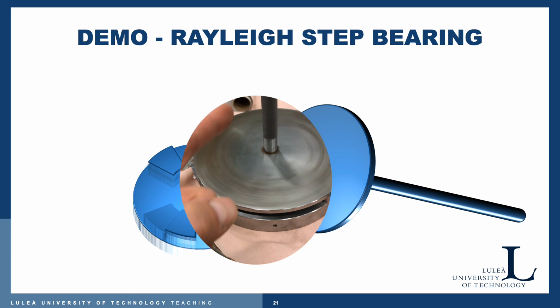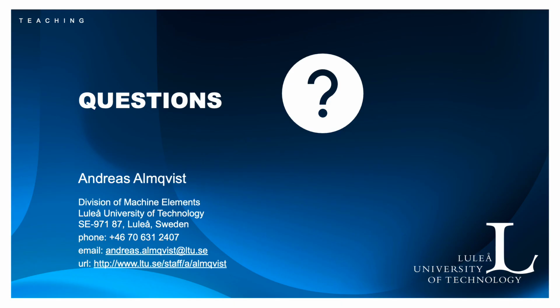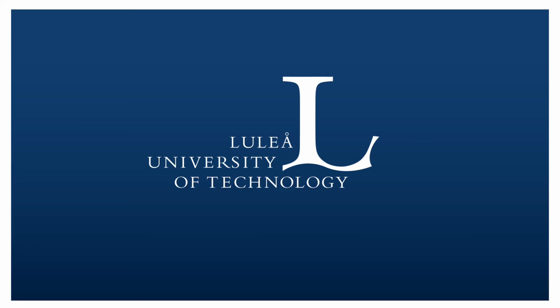And now we can hear that it can no longer generate that film of air. The friction caused by dragging in the air over that surface was actually stopping the motion of the collar to such an extent that the velocity became too low to fully separate the surfaces.